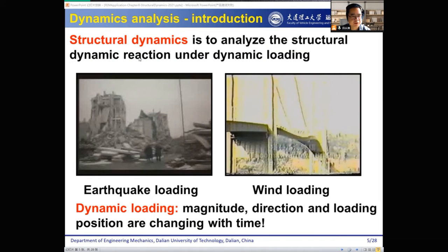So the structure dynamic analysis is to analyze the structure's dynamic reaction under dynamic loading. For example, what is dynamic loading? The earthquake loading and the wind load are two very typical dynamic loadings. A dynamic loading is one whose magnitude, direction, and loading position change with time.